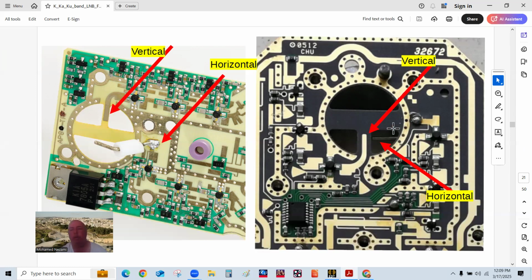Okay, and you can see it here. You can see just barely here is the other polarization which comes in here. That's a pin that is bent, and there's this bridge here in the board that has metallic copper grounded on the other side, and that basically acts as a short back for that one, where the cover in here acts as the short for this one. And this one, the same thing, has three-stage amplification as well.